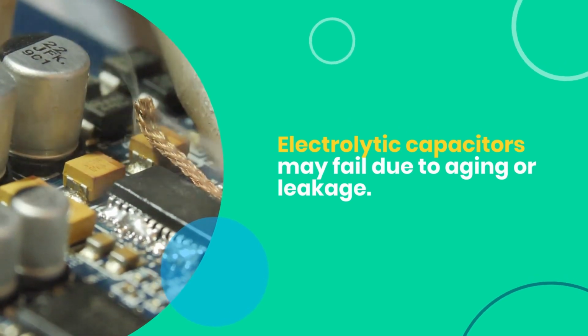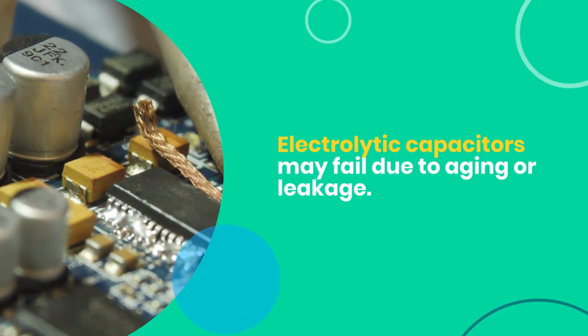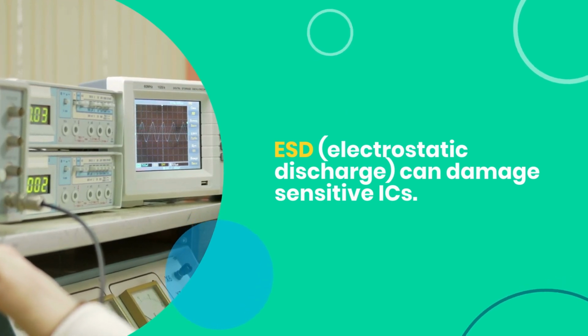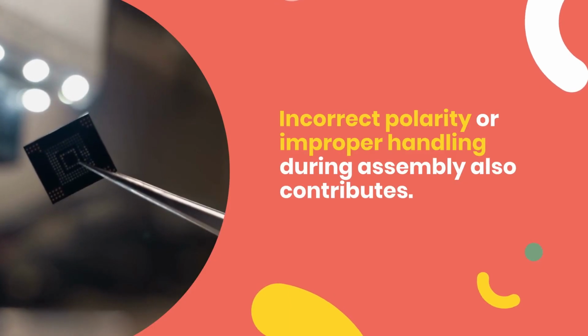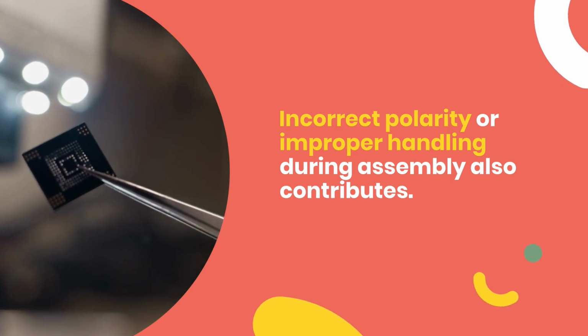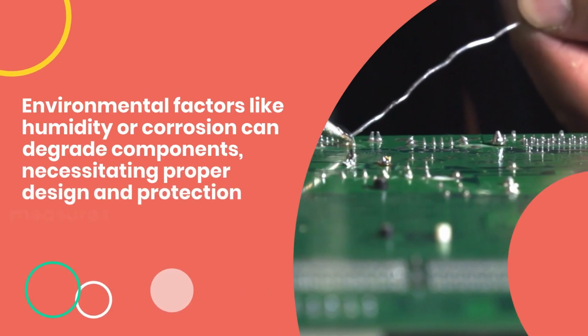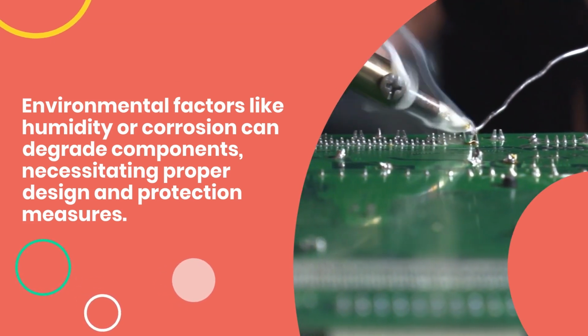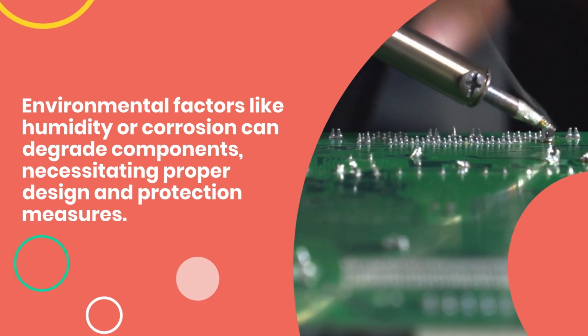Electrolytic capacitors may fail due to aging or leakage. ESD, electrostatic discharge, can damage sensitive ICs. Incorrect polarity or improper handling during assembly also contributes. Environmental factors like humidity or corrosion can degrade components, necessitating proper design and protection measures.